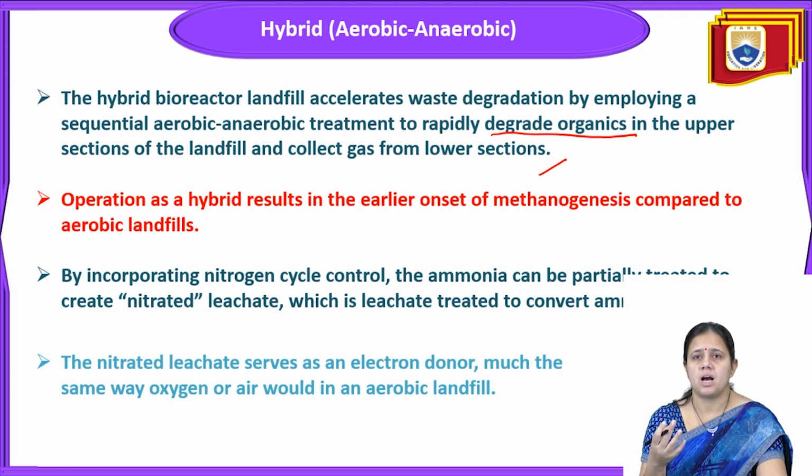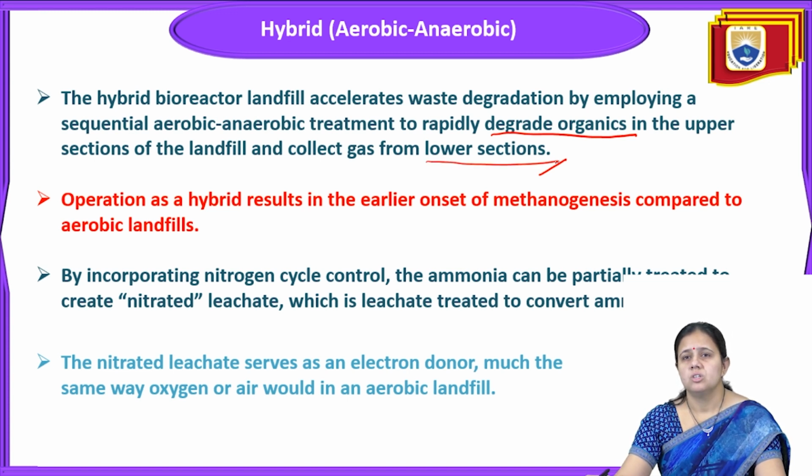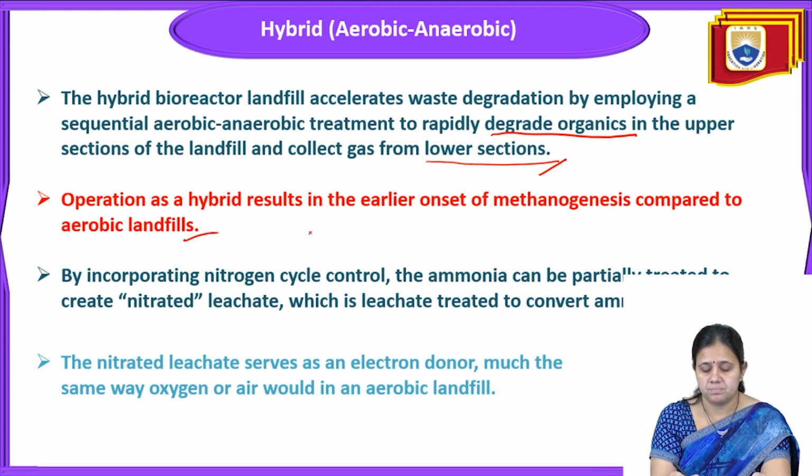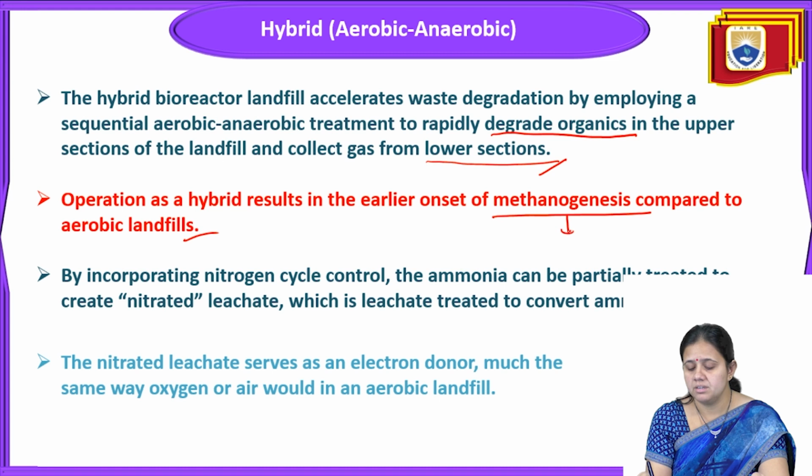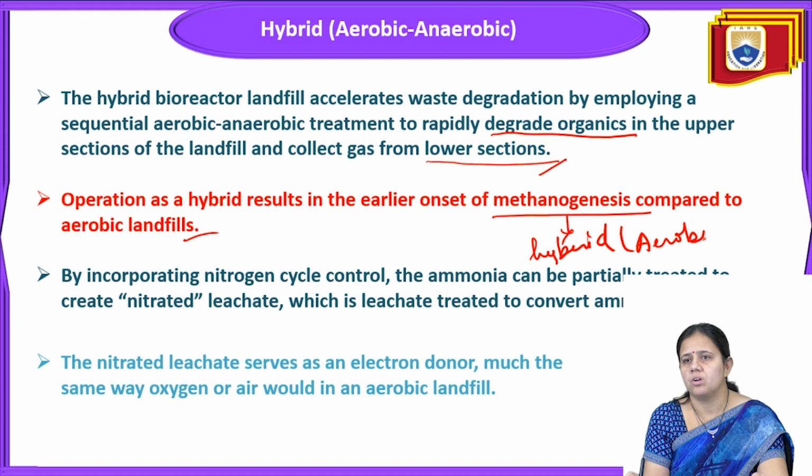It rapidly degrades organics in the upper section of the landfill and collects gas from the lower section. Operation as a hybrid results in the earlier onset of methanogenesis compared to aerobic landfills, because both aerobic and anaerobic processes are involved.